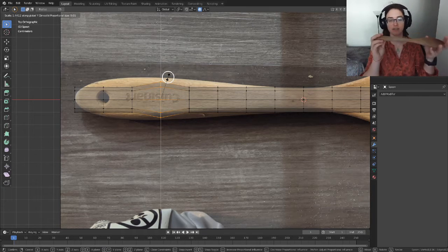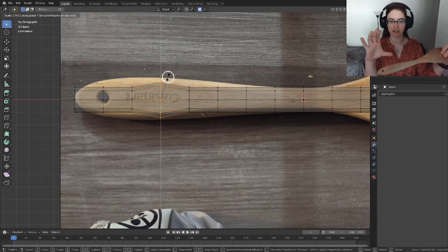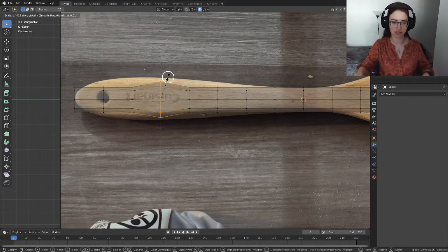This is important. If you don't do this, even though I'm in top view, I'm only going to be seeing the Y change. If I don't restrain that, I'm going to be making this part fatter and probably pieces further apart from each other. So make sure you're restraining your basic transformations.